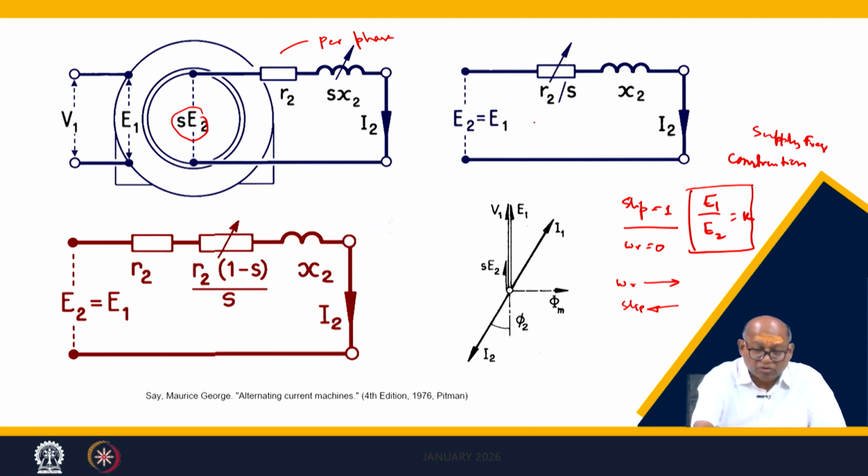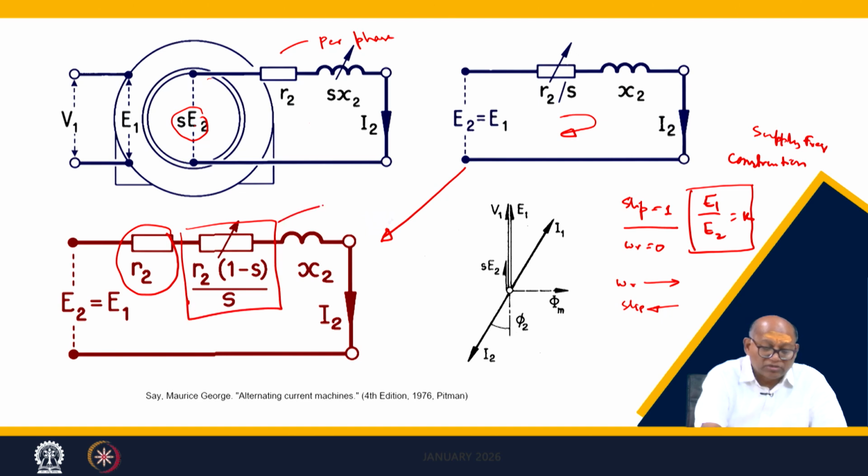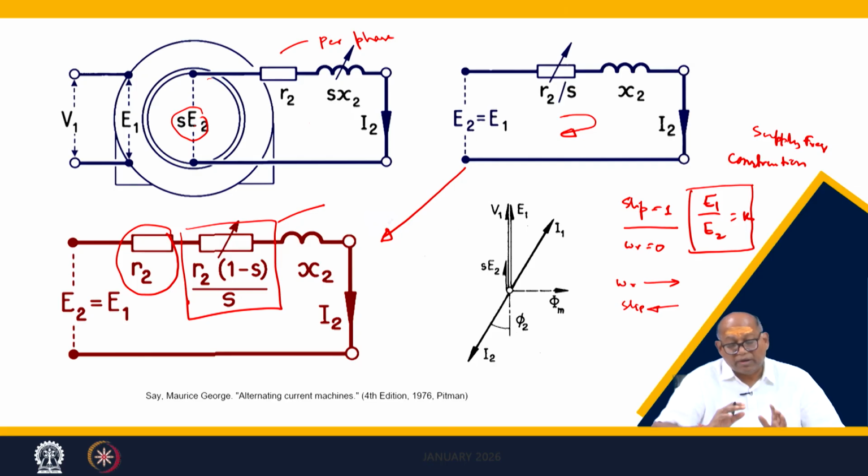So you can say the rotor circuit is this. In this rotor circuit, the frequency is different from the stator. But if you do little manipulations, you can divide by S everywhere, and the rotor circuit becomes this. As I told last time, this is at slip frequency, but this is at supply frequency. Just by dividing by S, you can assume that, so every calculation will remain the same. From this I have derived this. I have separated the rotor resistance and a component of resistance which appears here. This is responsible for torque, mechanical power and torque. So this is what we have discussed.